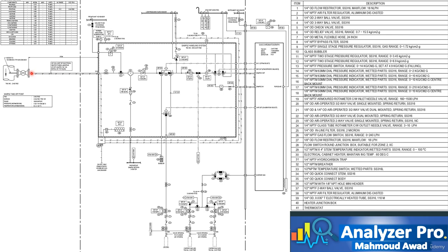Also, in this example we need heat tracing, but in this case we use electrical heat tracing and an electrical panel heater for better control of the sample and panel temperature.